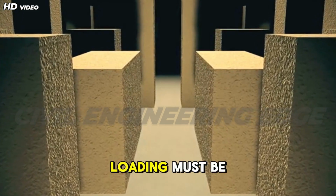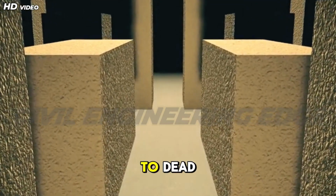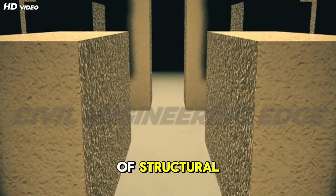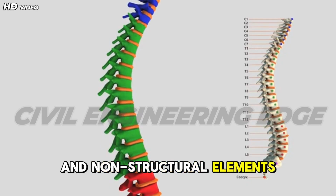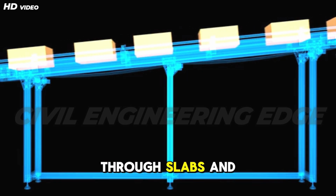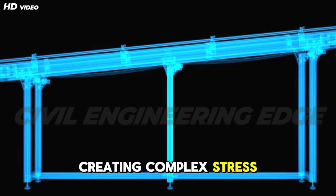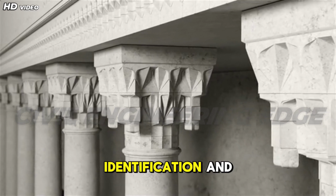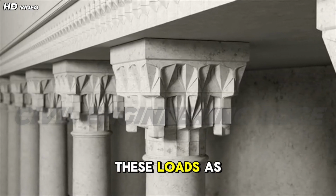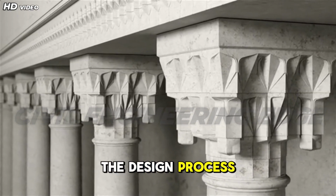Next, the nature of loading must be identified. Columns are subjected to dead loads from self-weight of structural and non-structural elements, live loads due to occupancy, and lateral loads from wind and earthquakes. These loads are transferred through slabs and beams into columns, creating complex stress conditions. Proper identification and combination of these loads as per design codes is a critical step in the design process.